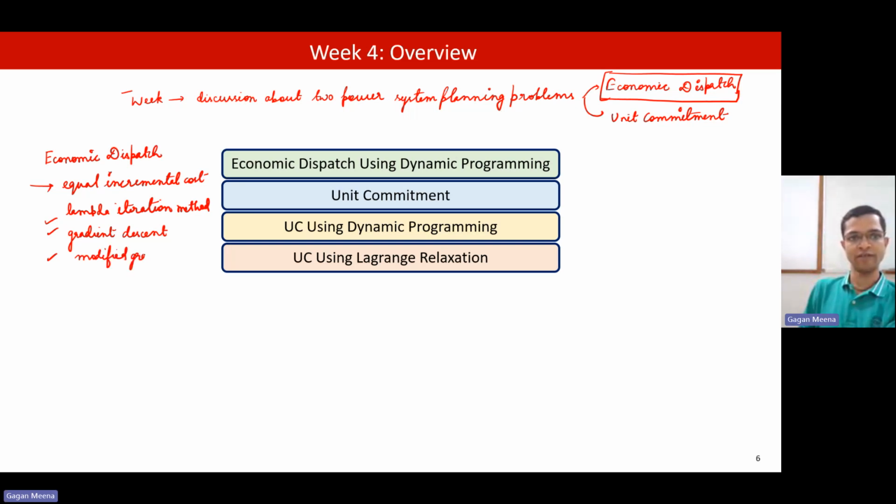to improve the convergence. We make one dependent variable out and reduce the size of the problem by two variables by removing lambda as well as one of the generations. So if there are three generators, then the variables will be only two generators, P1 and P2, and P3 will be written in terms of P1, P2, and demand. It becomes an unconstrained optimization in the modified gradient method.